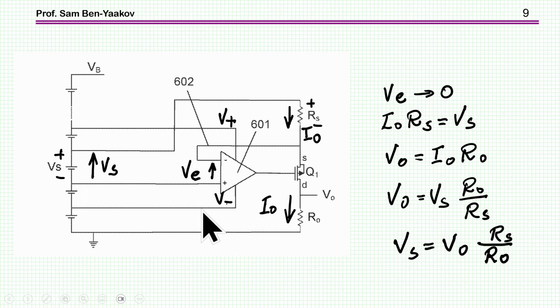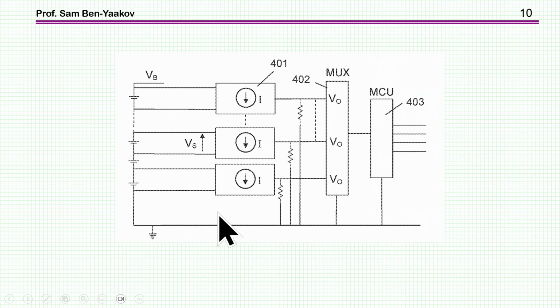And this voltage is riding on the potential at this point of this particular cell. Now, in an application, you can have this circuit for each one of the cells and then get the output through the load resistor, having a multiplexer, which will be sampled by the controller. And then, of course, you can use this for balancing the cells.